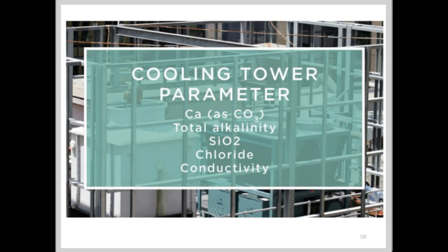Let's look at the requirements. Under Establishment, for cooling towers and evaporative condensers, projects should conduct a potable water analysis within 5 years of submission for certification, measuring at least the 5 control parameters listed here.